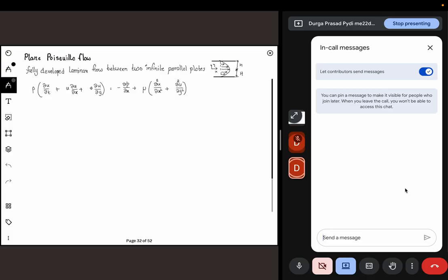Yeah. So I think up until here there are no questions, then we'll move on to the next one. Now the objective is, we have to solve the energy equation eventually, but in order to solve it, we have velocity terms inside the energy equation: u times del T del x plus v times del T del y. We need to find the velocities u and v, only then will we be able to solve the energy equation.